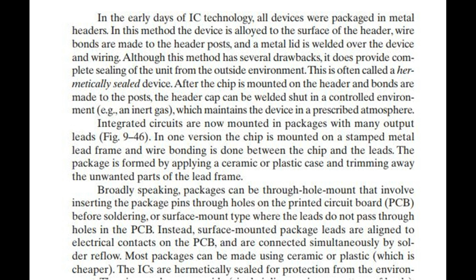Integrated circuits are now mounted in packages with many output leads, Fig 9.46. In one version the chip is mounted on a stamped metal lead frame and wire bonding is done between the chip and the leads. The package is formed by applying a ceramic or plastic case and trimming away the unwanted parts of the lead frame.